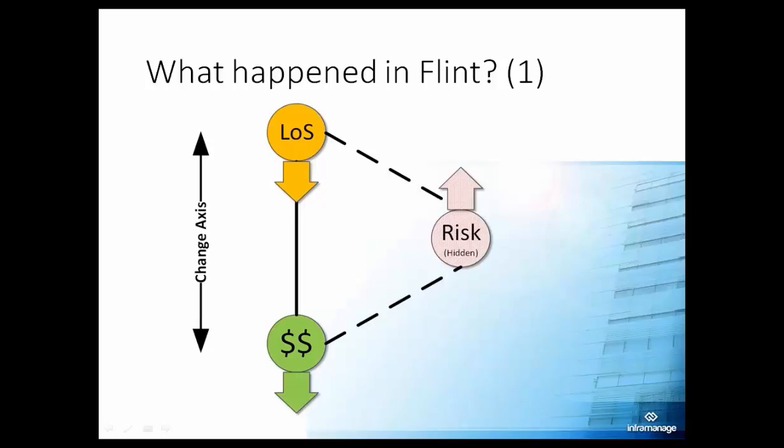And I think the only time we really see water utilities going to great lengths to get condition assessment is if the risk is extremely high. So if you have a pipeline that's like the main transmission into your system, and it's under a railroad track or an interstate and not encased in another pipe, and the consequence of that rupturing would be tremendous, you could hire somebody to come in and do a visual inspection on the inside of the pipe, as well as collecting wall thickness data and that sort of thing. But it's not necessary unless you have a very high-risk situation, especially if you're a small utility. A larger utility might do that, but for a smaller utility, that's probably more information than you need.